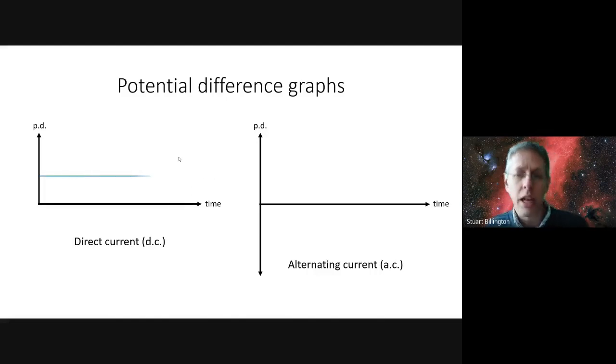You'll notice that for the alternating current one, though, I've got a negative side to the battery. And you'll remember that when we did the bulb practical in class, I asked you to use lots of potential differences, 2, 4, 6, 8, 10, and then I asked you to pull the wires out of the power pack and swap them over and push them back into the power pack again. And suddenly the voltmeter starts saying -2, -4, -6, -8. And all that minus sign meant was that it was the other terminal that was now the negative one. The positives and the negatives are swapped over, and it caused the current to run in the opposite direction.